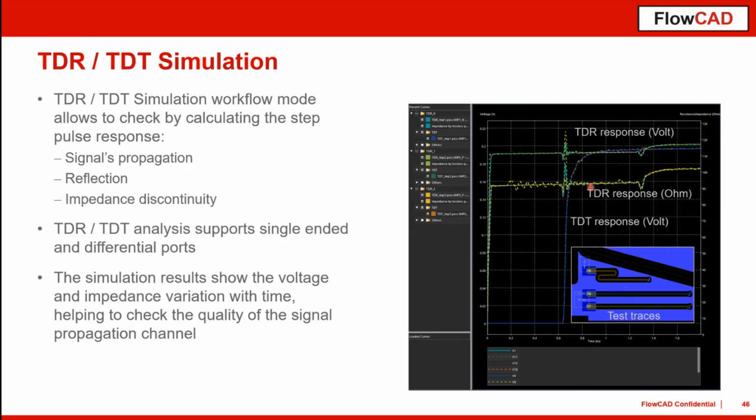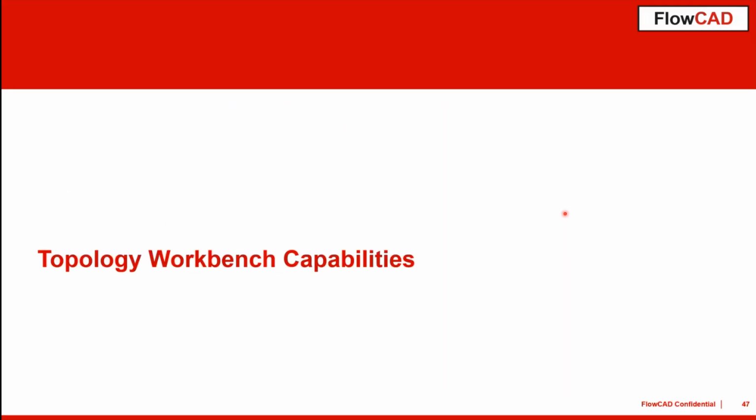Also, the setup is quite simple because you just have to assign the ports for the transition where you drive in your TDR pulse, and then on the back side you may also set some ports to calculate the transmission. The blue line here represents the transmission of the TDR signal. So you can also see from this how much the attenuation of your traces can be analyzed. So that was a brief overview of the SPEED EM analysis capabilities.